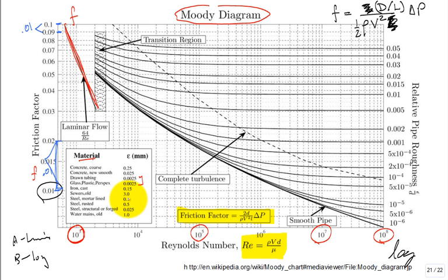Okay. Then what they do is they have a series of curves that are out in the turbulent region. The curves depend on different values over here. What are they plotting for? Like this is the curve per 0.002. But what does that 0.002 mean? It's the relative roughness, epsilon over D. True? So this is a rough pipe with rough walls compared to the diameter. This is a smooth pipe down here. And guess what this bottom curve is? Oh, look at there.